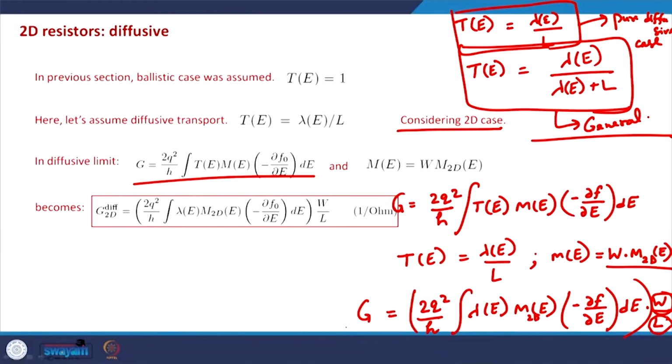So we cannot use our conventional theory of electron transport in the ballistic case, or even in the diffusive case, or in intermediate cases when we have some scattering but the conductor is also not extremely long, it is not a pure bulk conductor, it is in the intermediate length scale. In that case also we need to start the treatment of electron transport from the basics, like here.